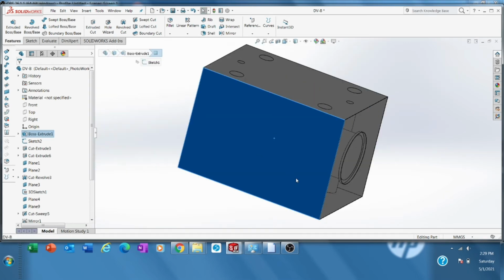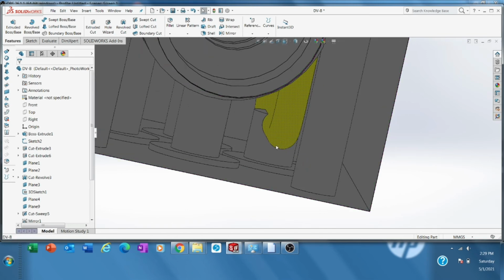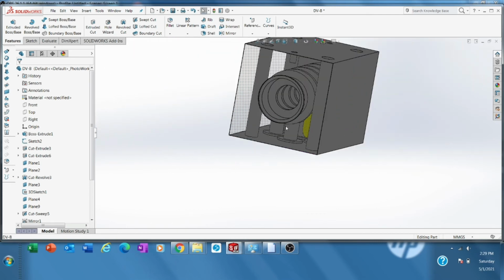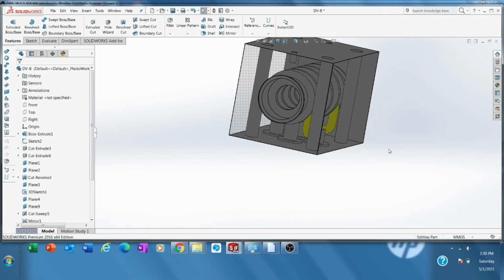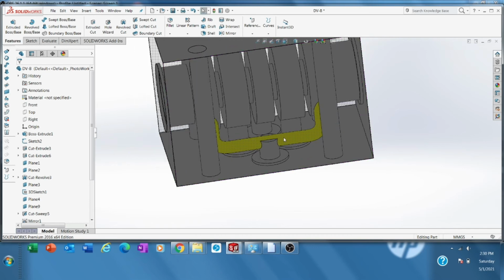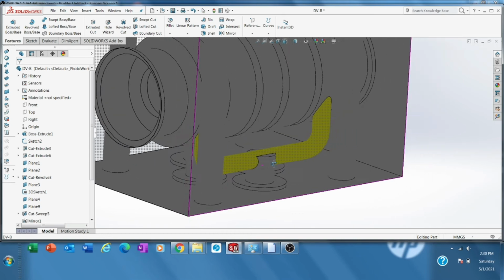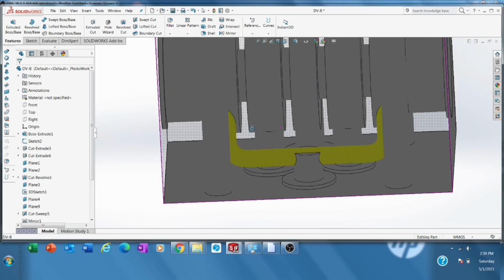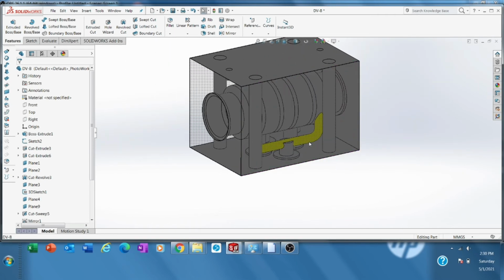As you can see, this is the room, and then there is a room here, a pump port, that is not possible to make by machining, as I explained to you, only by wax casting. So it manipulates the direction. The pump flows from here into these two rooms. If there is no energy to the spool through the coil, the force balances left and right, and there is no flow. That is the case for open center.